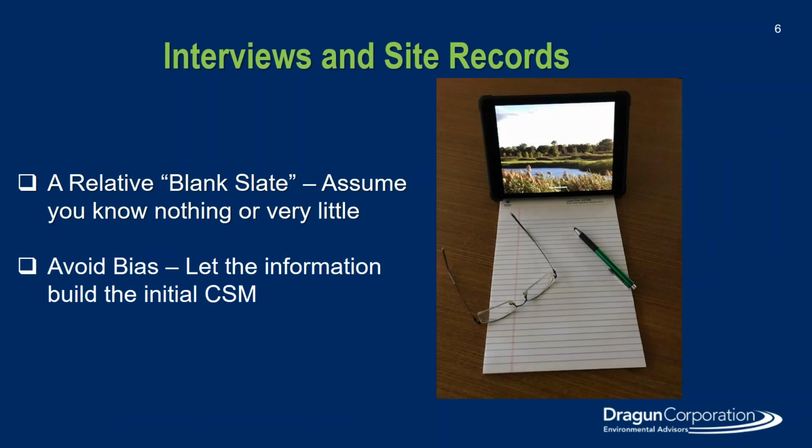Often we're given previously conducted reports about a site, or you may have even conducted a site inspection. While these are really important in the overall conceptual site model process, don't let these things cloud or influence your thinking about the site too much too early in the process. Think of your site as a blank slate and let your research of records and interviews start to draw the conceptual site model picture.